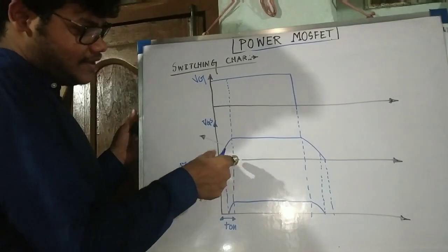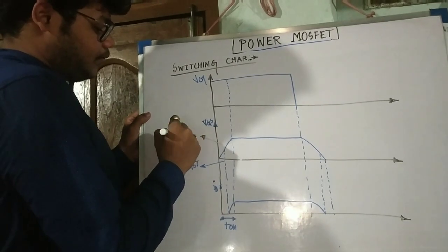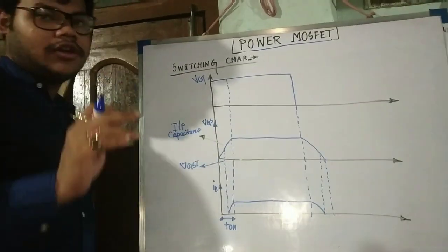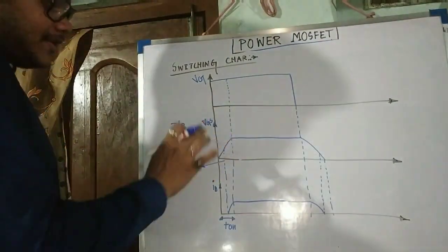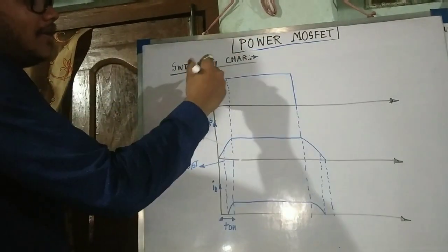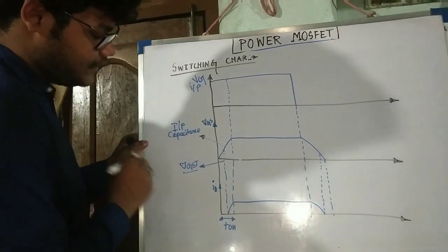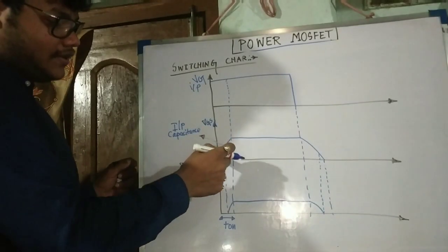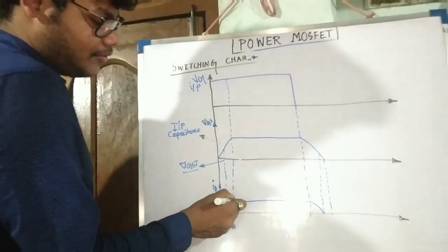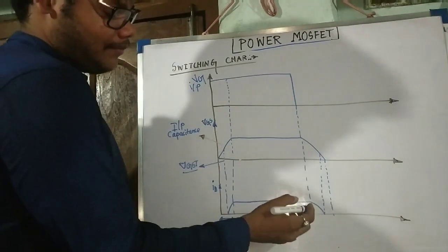This delay in the gate to source voltage is because of the input capacitance effect, which we have already explained. The input capacitance effect is not allowing VGS to rise sharply like your VG, which is your applied input voltage. And this is your VGST, that means the threshold voltage. After the threshold voltage, the drain current starts rising. Again, suppose the device is now on. Now what happens?